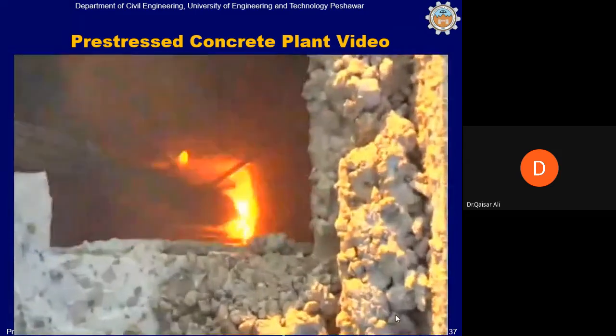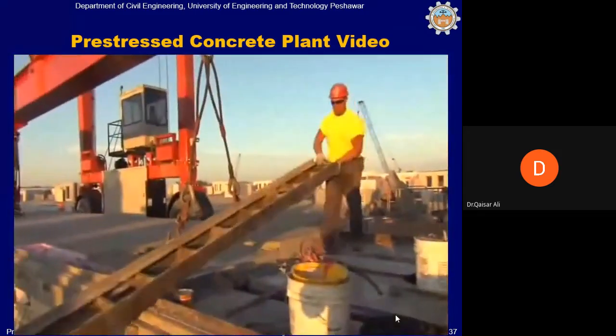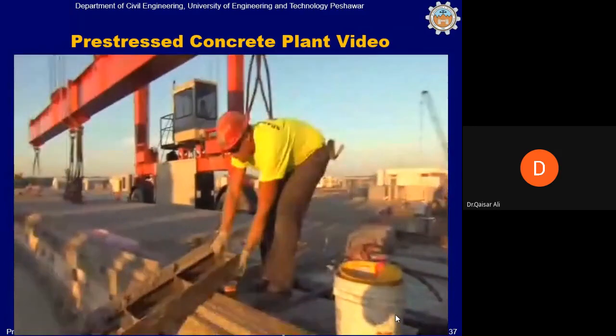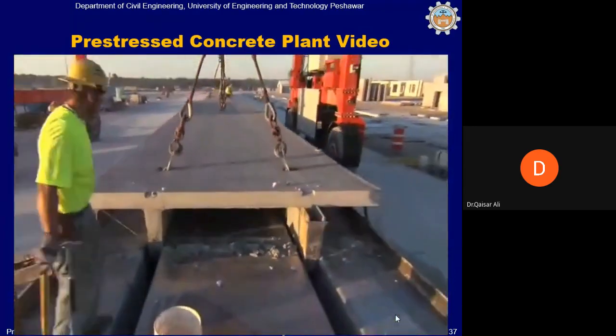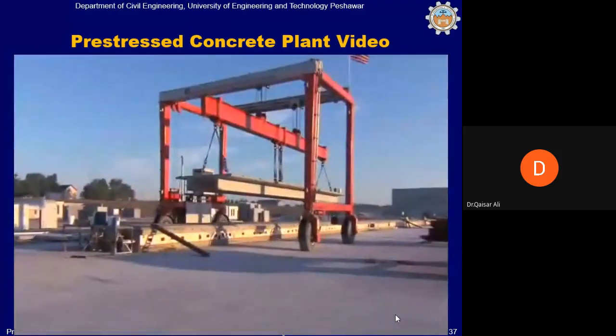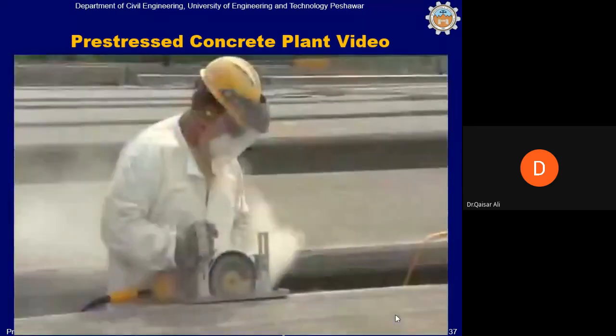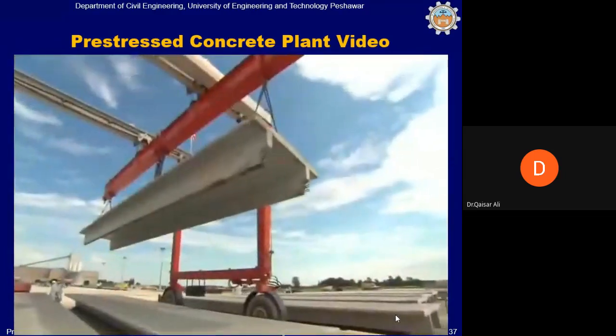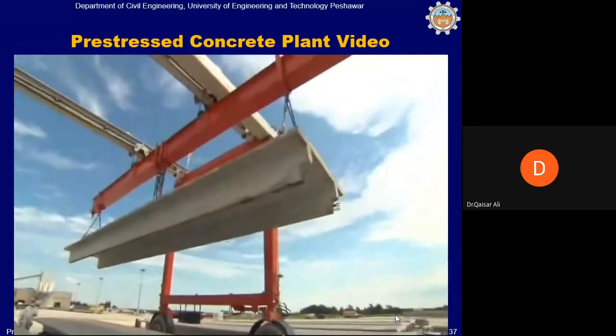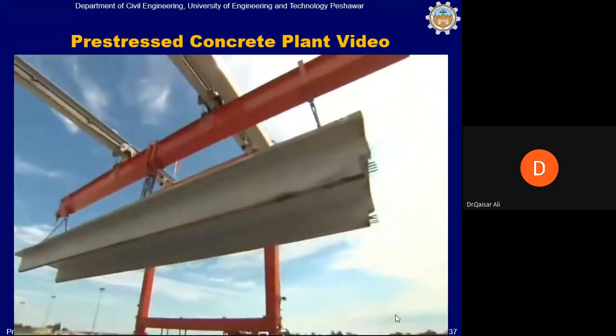After all the strands are cut and block-out formwork has been removed, the Ts are stripped from the form. Cables are attached to the lifting devices, and each piece is removed and transported to a detailing area for any minor cosmetic touch-ups. Also at this time, the QC department does a post-pour QC check on each piece that is brought to the detailing area.